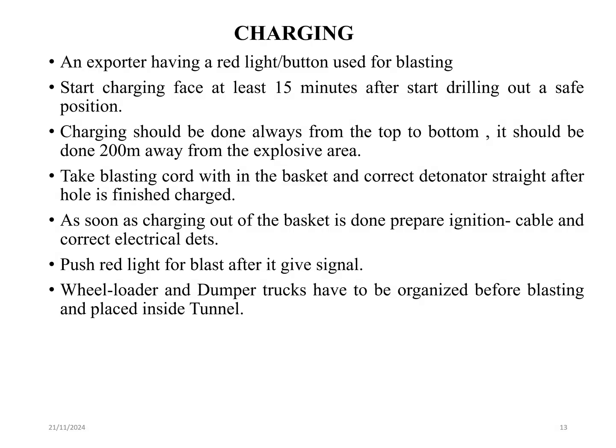Charging. This involves preparing the explosive charges for blasting. The process includes placing the detonators and blasting cords in the drilled hole, ensuring that the charges are correctly positioned for effective blasting. Safety measures are strictly followed during these steps.